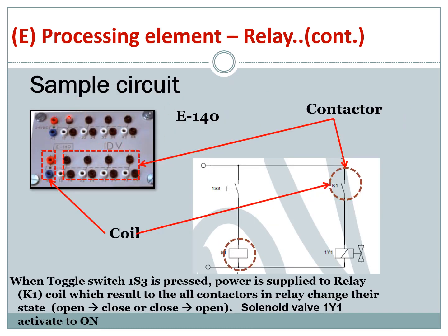This is a normal relay circuit used in electropneumatics. You have a coil inside. The coil we normally name K1, K2, K3, depending on the number of coils. S3 is a switch attached, so you can attach a switch here to the connectors. And when the coil is magnetized, it will activate the relay. You can read here.